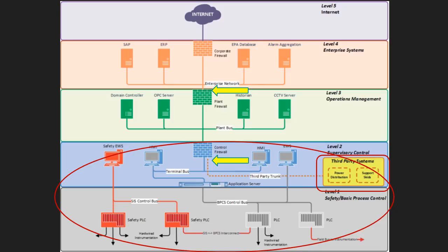Usually you'll find that, when you have a segmented Purdue network, a lot of times the operations people manage the control firewall, or at least dictate how that control firewall is configured. IT controls the enterprise network firewall up here between the corporate and the plant side. Again, with instructions from operations usually, but generally OT owns this one, IT owns this one. L1, L2, there's no firewalls there.